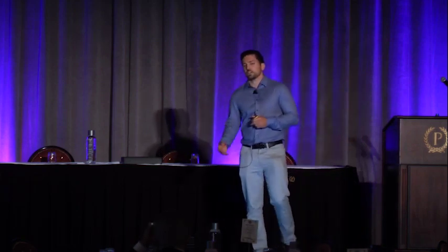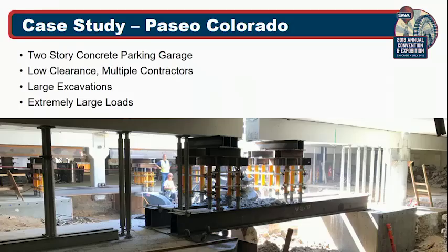So what we ended up using was a mixture of modular scaffold systems and pre-manufactured posts. And for this contractor, he had these posts available, so lucky it was already in his inventory. But because of this versatility of these types of systems, we were actually able to fit all of the shoring in between the sill beams and transfer the load adequately. And this is just a good example of where the versatility of your guys' systems actually go above and beyond that of the pre-manufactured systems. And if it wasn't for this type of system, we wouldn't have been able to accomplish this job.